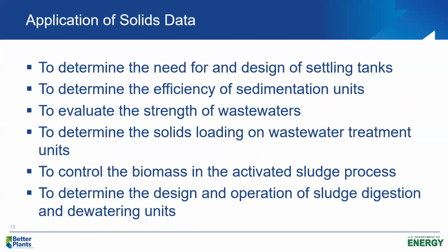Solids can be used in a lot of ways, help us to design settling basins, determine their efficiency. Obviously, suspended solids content of the wastewater gives us an indication of strength. It helps us to determine the solids loading on treatment units. An example there is when we design the secondary clarifier in the activated sludge process, a key design parameter will be the solids loading. That solids loading will be in pounds of suspended solids per day per square foot of surface area in the secondary clarifier.